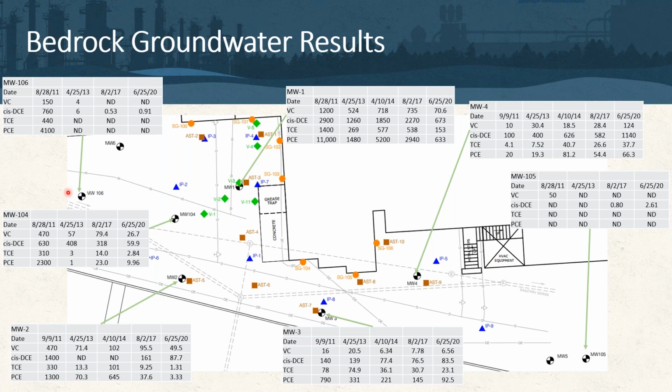Source monitoring well number 1, located in the center of the page, looking at prior to injection 12 ppm of PCE and ppm concentrations of daughter products. And again, looking at that managing of mass, we see that even 10 years after implementation, or 9 years in this case after implementation, we have continued reductions and an overall downward trend throughout the history of the site. And we can see from periphery wells as well here, MW2 at the edge of the creek, looking at ppm concentrations coming down from the initial sampling down to low-level ppb concentrations, nearly meeting the MCL in cis and vinyl chloride. Next slide, please.